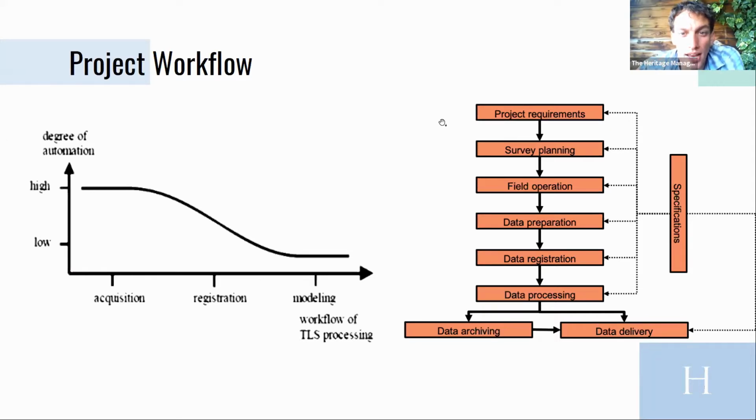Even with a laser scanner, and notwithstanding the fact that we do a lot of highly automated data acquisition, we still have to plan our data acquisition because of the cast shadows that we will generate, because we have to position our laser scanner in 1, 2 or more places. We have to set our targets and stuff like that. That requires a certain amount of effort.